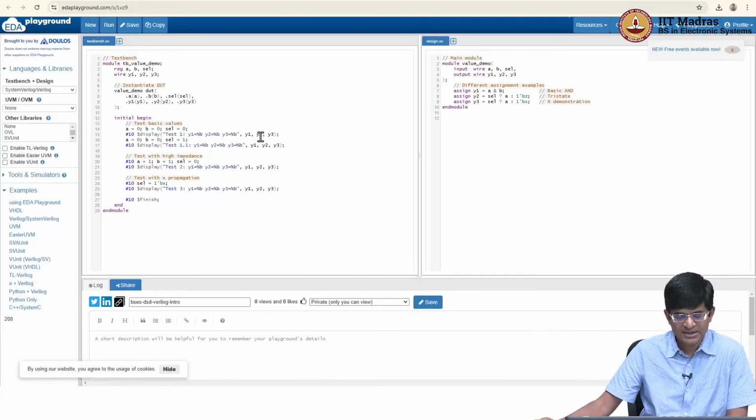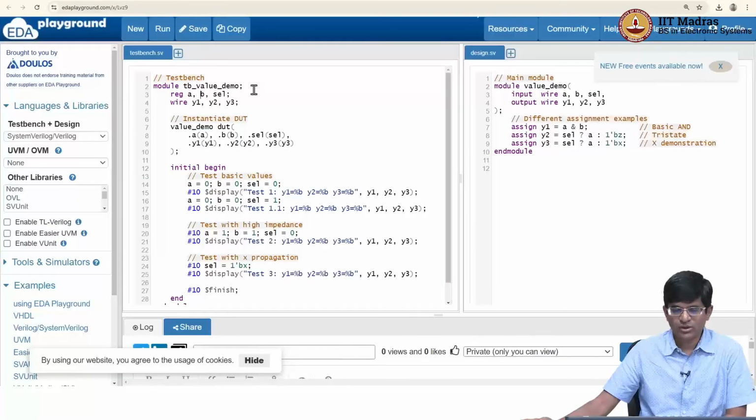So, with all of this in mind, I am going to show an example of a simple Verilog code, right. And so, as you can see over here, this essentially corresponds to an example of what a Verilog code might look like. It's a very specific kind of code, right. What we have over here is a module. I've given it a name, but you will notice that it has no parenthesis after the name. It has no inputs, it has no outputs. It is a so-called test bench, and we'll be talking more about it later.